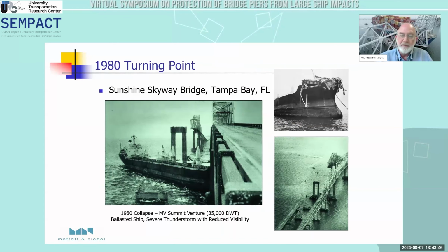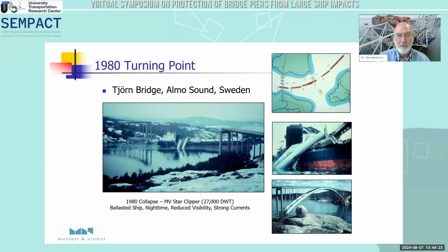1980 was a turning point. The Sunshine Skyway Bridge in Tampa was hit. 35 people were killed. The lower left shows a picture of the accident. I'd like you to be aware that the vessel did not hit the main pier. It hit the approach pier. Twice as many bridges collapsed due to ships and barges hitting approach piers than the main pier adjacent to the channel. The upper right shows the bow of the Summit Venture, a minor crease in the hull. That ship came in, took on a load of phosphate cargo, and took off 2 weeks later.